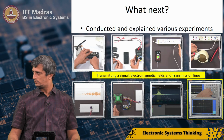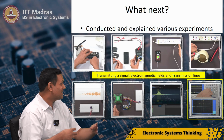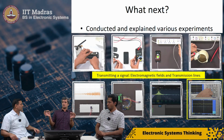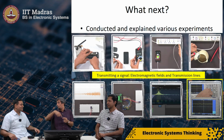Obviously, on the analog side, if you have high frequency circuits, maybe from one amplifier to another, if you have two different ICs with a connection between them, that would act as a transmission line. Okay, so essentially you're saying that what is supposed to be a simple short circuit between two points, is it? Yes. And this is what we saw in our course here with this big loop of wire.